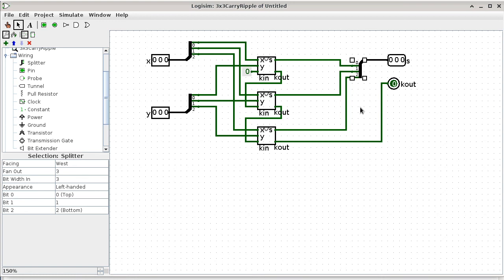Say that one more time. So if we're doing the addition that we did earlier, the 1001 plus 1110, or 1111, whatever it was. Well, that was a 4-bit thing, so we have to shrink it into 3-bit. But the point is, our output will have 4 bits, yes, because there's a carry on the last adder.